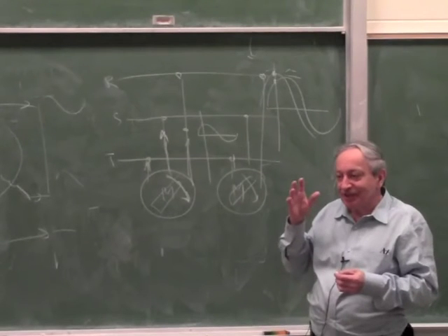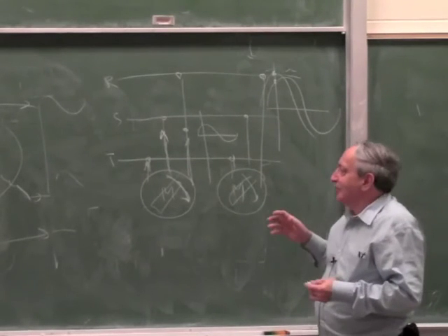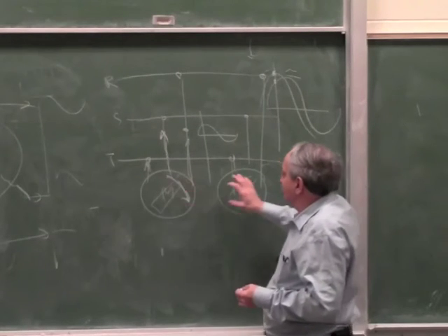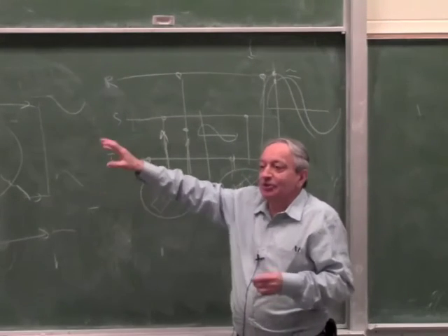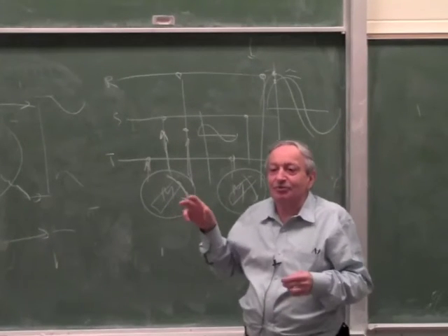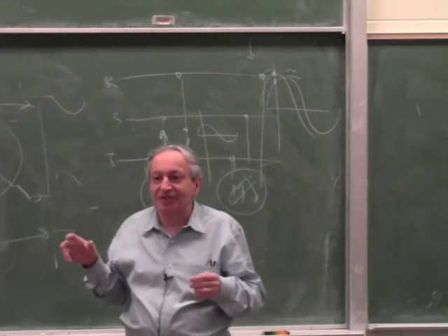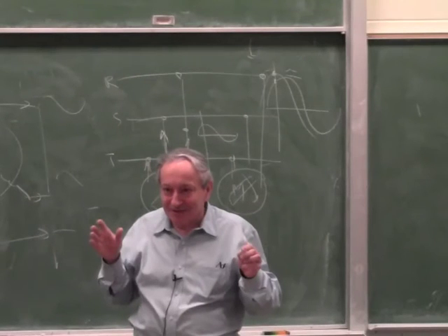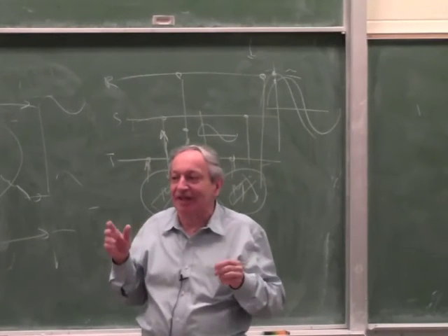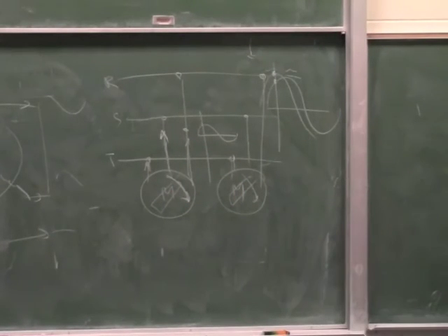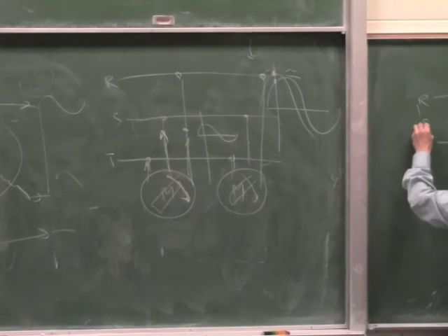So it takes a minute for it to sink in, because then you realize that this works like a mechanical gearbox. Since this is locked to the rotating field, all the motors in the country are locked to the same rotating field. So all the motors in the country which are synchronous behave as if they were geared together. Once you start thinking about it, you realize that that's the only way the grid can work. Because the electrical grid has these three wires, R, S, and T.